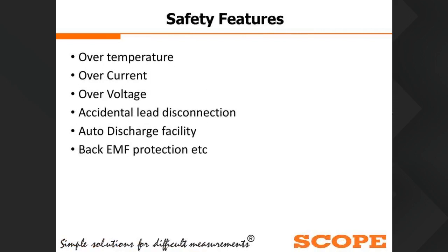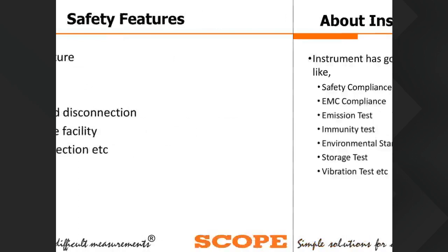Now the safety features that are important during measurement or testing: over temperature, over current, over voltage, accidental lead disconnection, automatic discharge facility after the testing, and back EMF protection. These are the safety features that we have added in our instrument.